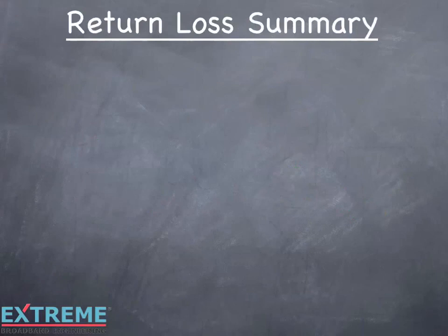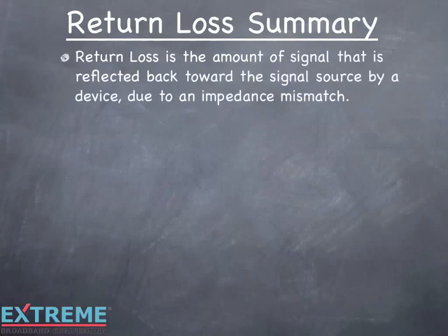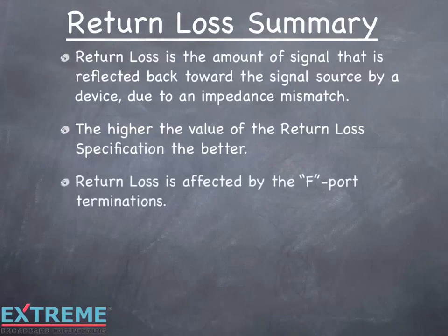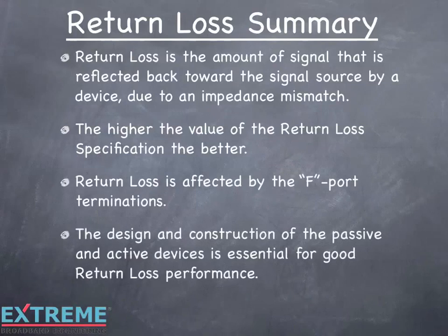Let's review what we've learned in this training session on return loss. Return loss is the amount of signal that is reflected back towards the signal source by a device due to an impedance mismatch. The higher the value return loss specification, the better. Return loss is affected by the F-port terminations. The design and construction of the passive and active devices is essential for good return loss performance.